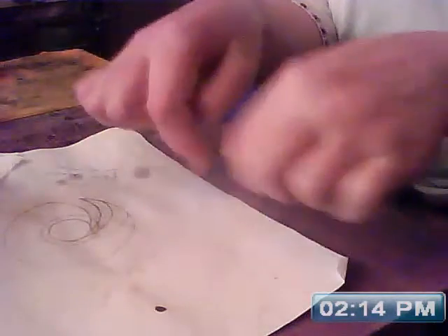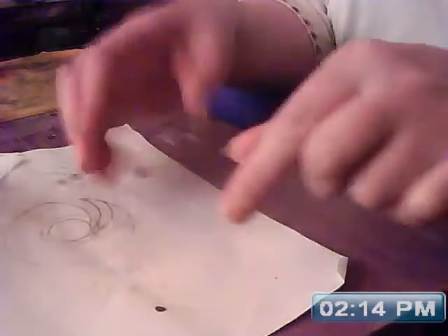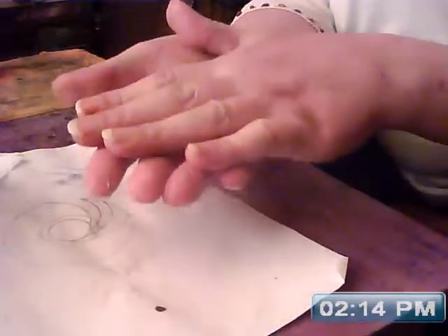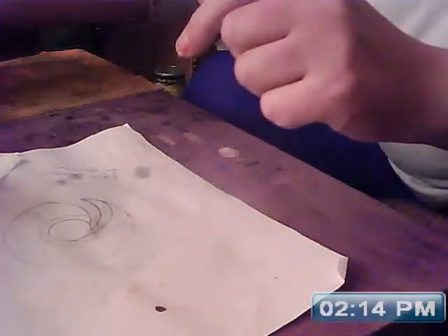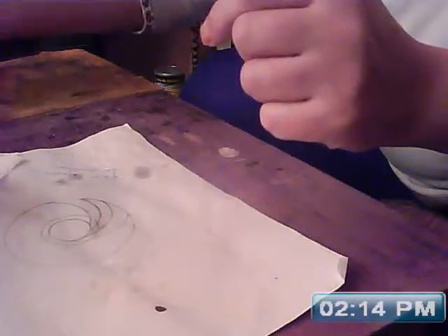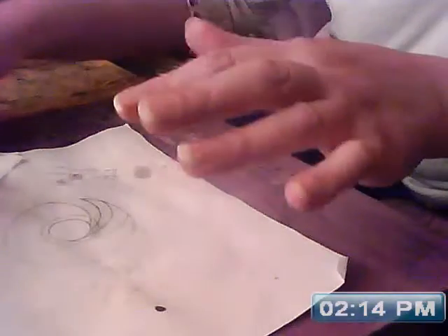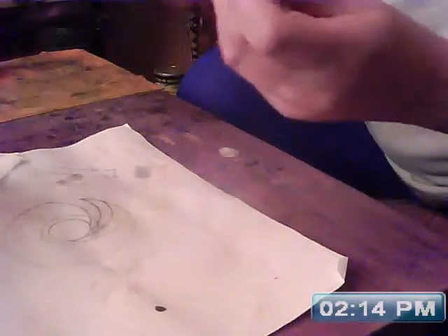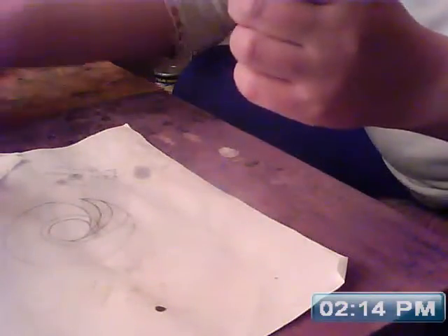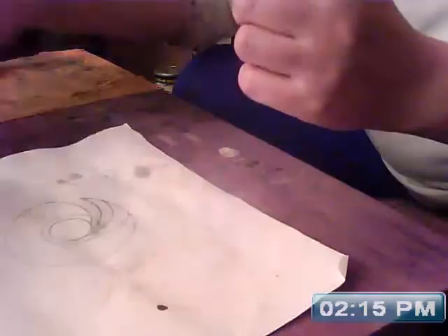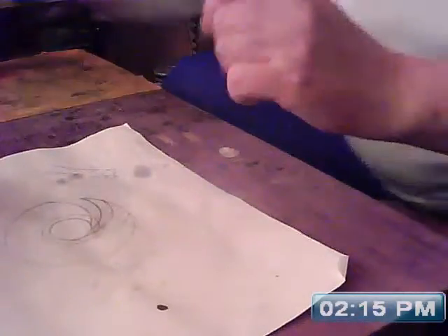The cover is just what goes on top of the fan and gives it support. As with the blades you've just been looking at, it has a little cover that snaps on the top, and that cover keeps the air inside while the rotor is spinning, to accelerate it. I made the covers so that you can just clip them on top, because I didn't want to print them with the lid on, as there would be support material inside and it would make a mess and be really difficult to get out. It's just as easy to print the cover separately and put it on later. Plus I'm saving plastic by doing that, which is more environmentally friendly.